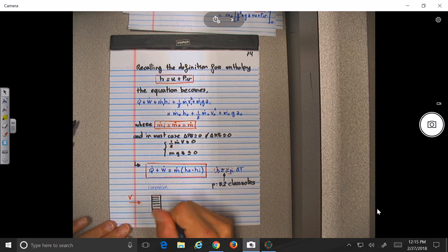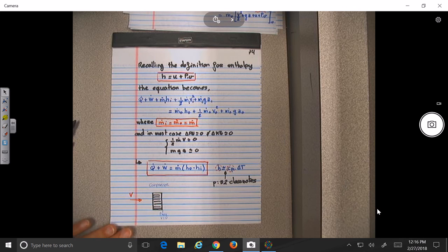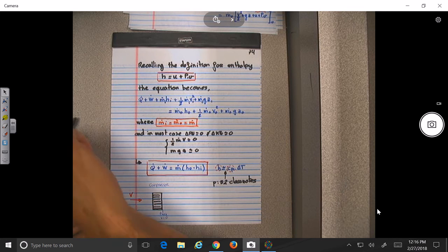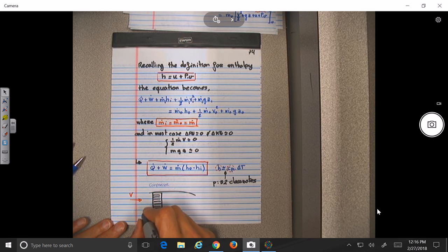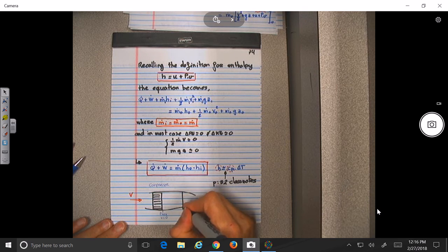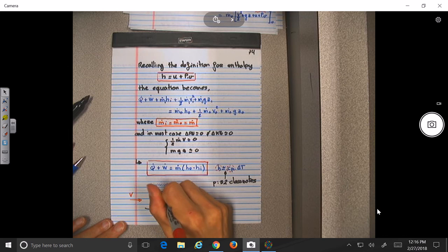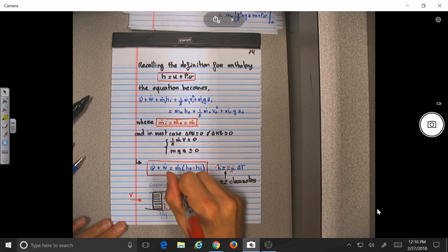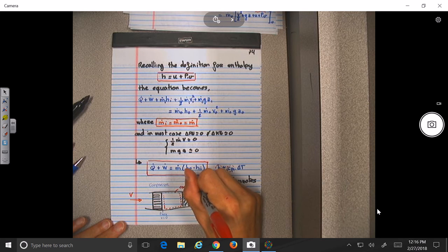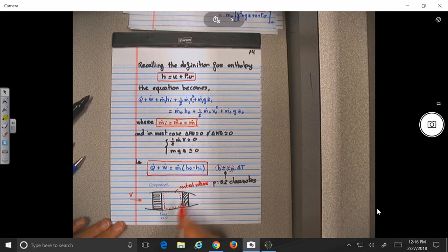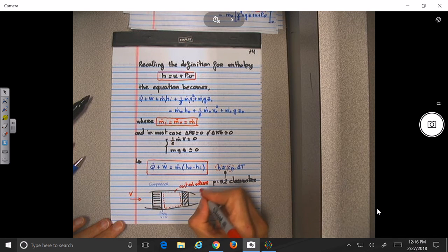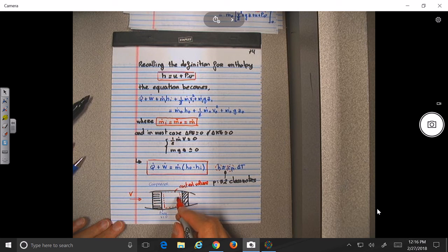Then ideally at the end of the compressor, what's gonna happen? The pressure is gonna be maximum and the velocity should be 0. So you transform all the kinetic energy into pressure, no? Now, what do you have in the middle? This will be, if you want, your control volume. So into the control volume, you have the work done by the pressure, because this is constant V, so P max times V. It expands over here if you want.